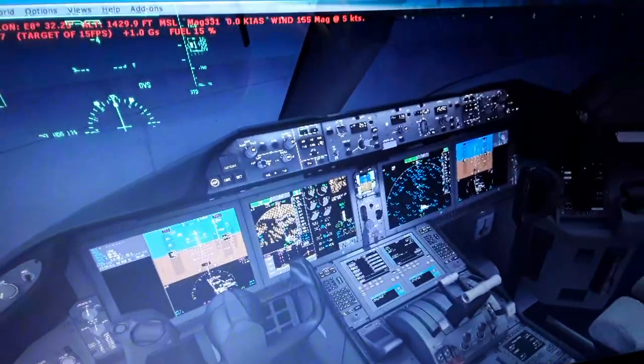The aircraft also flies at an airspeed about 2 or 3 times faster than at sea level, so we have a higher intake of air from the front fan for compression and combustion in the engines. So we have a different fuel mixture requirement every second, which is adjusted automatically by the FADEC, instead of manually as you do in a trainer propeller aircraft or turboprop aircraft.